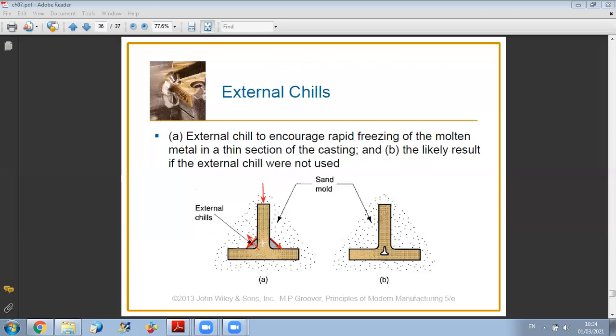In this way, this region will solidify faster, and because this region is far from the riser, we desire it to solidify faster. So this will allow us to minimize the possibility of formation of voids, because here, as you can see, you have the possibility of void formation in these zones, since they are far from the riser.